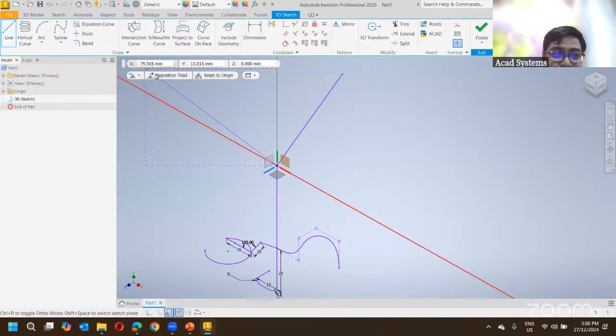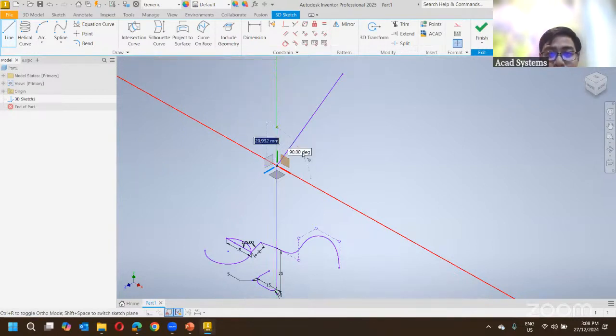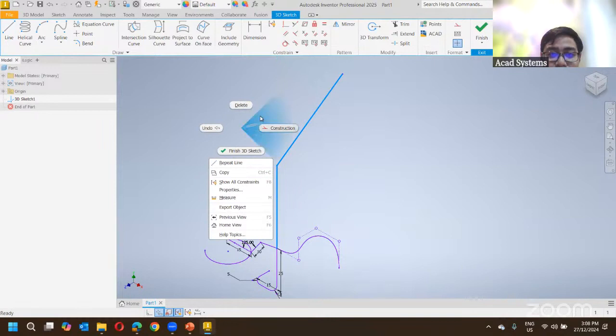But when you turn on the option for a coordinate like this, the precise input, you will find that you can no longer input the length and also the angles. So for that, you need to turn off this precise input over here. So just click at the mini toolbar options here, and then you can click close. Now my length and also the angle option can now be input. But for this case, let me just delete this one.